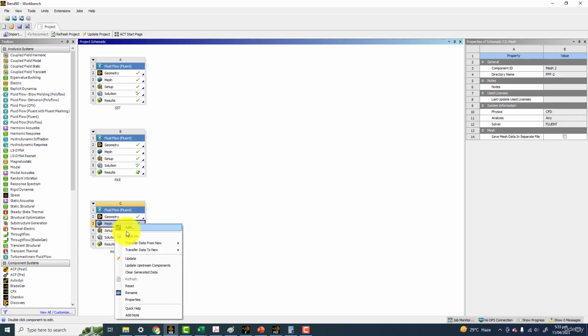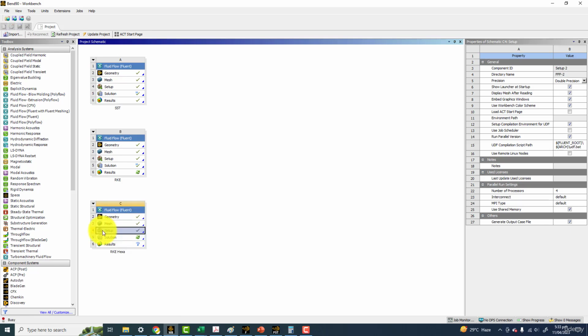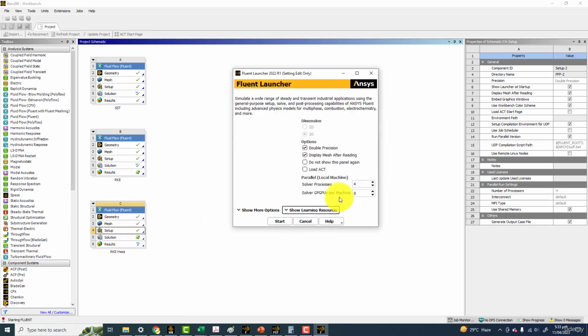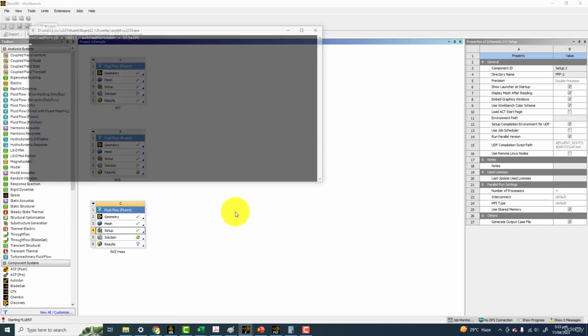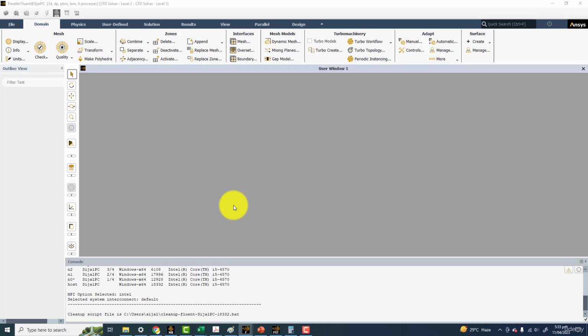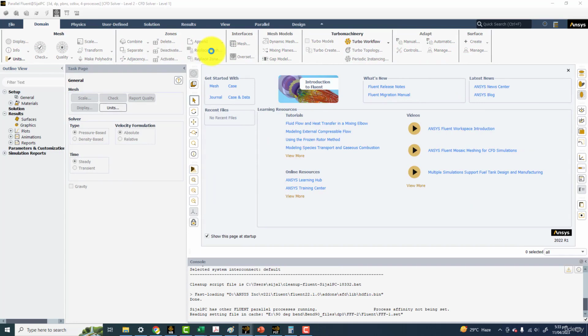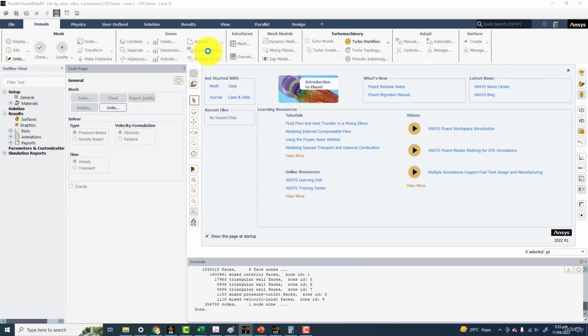So what I'm going to do is that I can basically open setup. I think we can get that option here, or maybe not. So let me check, or maybe we have to create the Fluent part separately, and we have to set everything again from scratch. So if I can replace a mesh file, then that would be a good thing. If this is a gray color, then I cannot replace mesh file. So just wait for this thing.